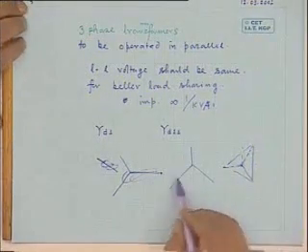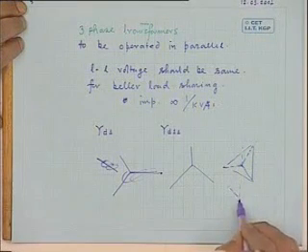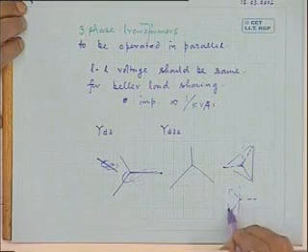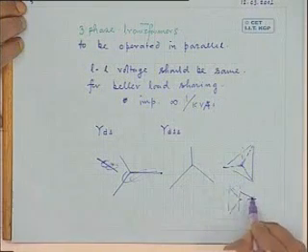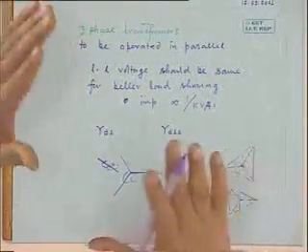With respect to the artificial neutral. But in case of YD11 connection, this triangle will be like this. So A, B, C here and A, B, C here, they are shifted. So if you try to connect them in parallel, there will be a large circulating current, as if you are trying to connect two sources which are not in the same phase and same magnitude.